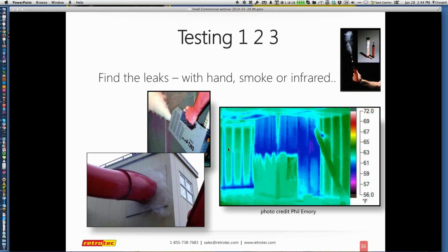And on the left, they did actually install the insulation, but the blue section is showing me where I actually have air infiltration that's moving across the bottom and up near the actual framing itself. So you get a lot of effects when you combine your infrared and the blower door together, and you don't have to have such a large scale difference of temperatures in order to have an effective evaluation.